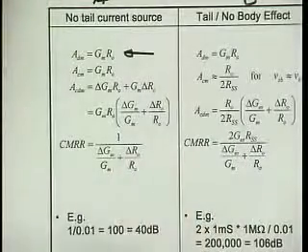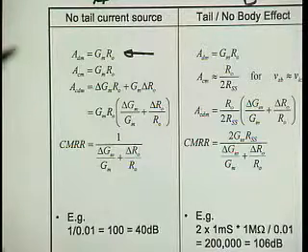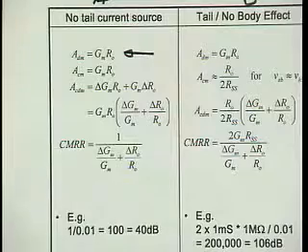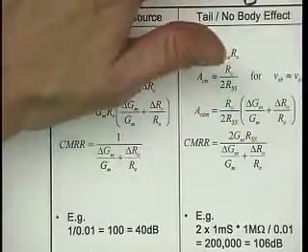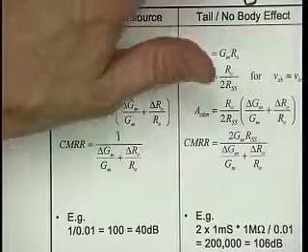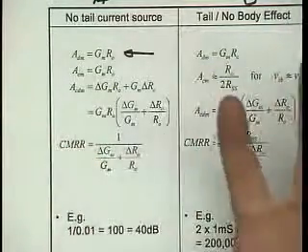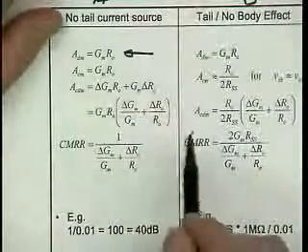we've done mismatch analysis before, and we said that it's kind of difficult because very often we have to go back to the nonlinear equations because not all the parameters are available. When they are, we can map the mismatch parameters easily to small signal parameters. It's much easier to perform the matching analysis on the small signal model. But of course that requires some insight. So here it works, so I do it this way, and in other cases I just go back to the square law model equation.